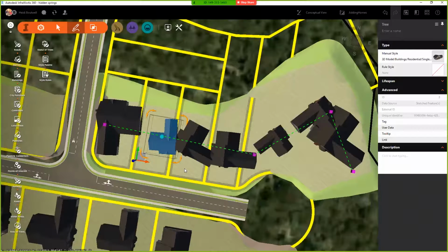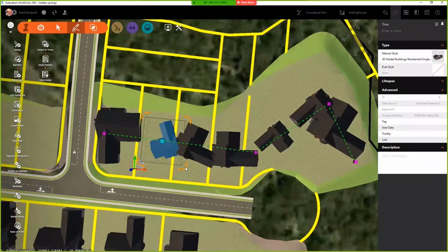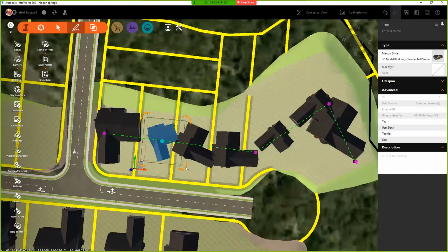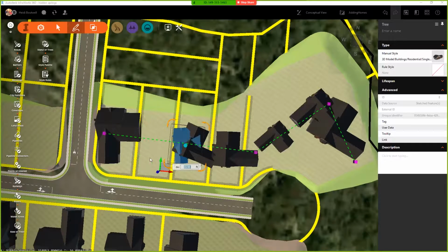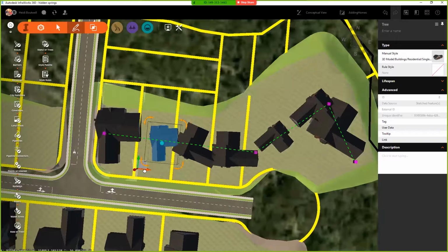Actually, let me type in the angle. Get back here. 180. Get it to flip 180 on me. There we go. Yeah, so you can type into those toolboxes. You just start typing. You get the gizmo over here. The gizmo moves it everywhere, or you can go up in the Y only, or maybe the X only once it's lit. Okay, and this is the Z, the blue. But the big box, we'll drag it all over. And the little orange arrows are your rotationals.